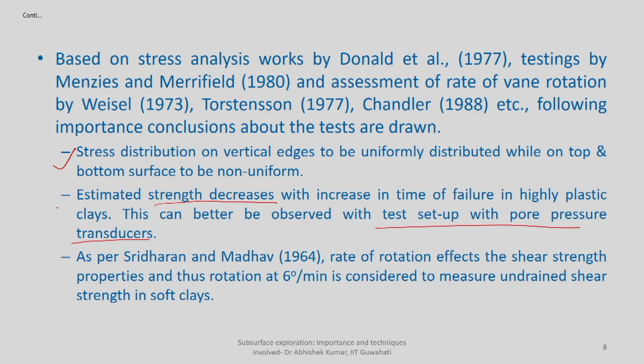So, they standardized and suggested that a 6-degree rotation in 1 minute can be considered optimum, or can be standardized, when you are going for measurement of undrained shear strength of soft clays. So, this is some kind of standardization based on the work by Sridharan and Madhav after 1964.